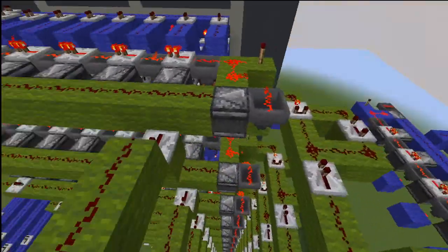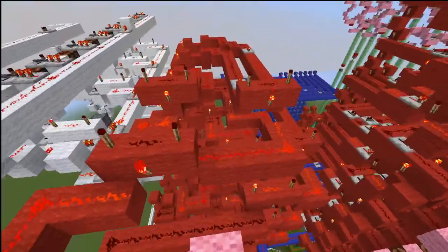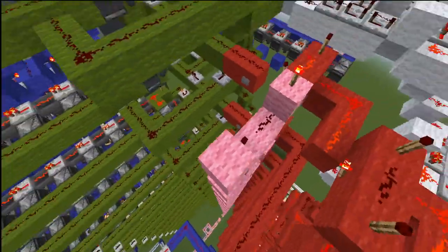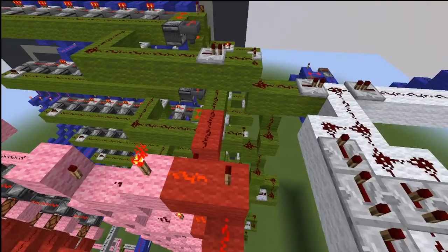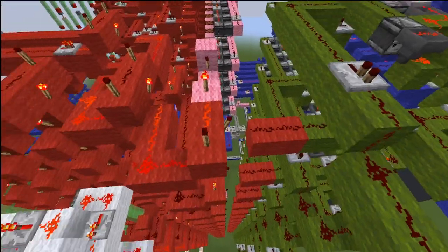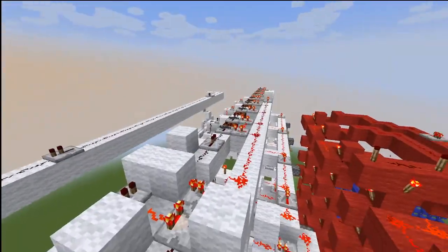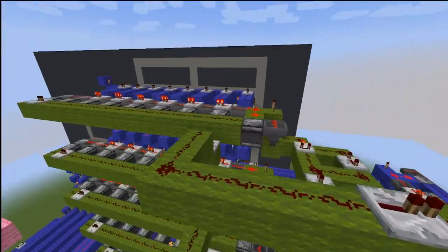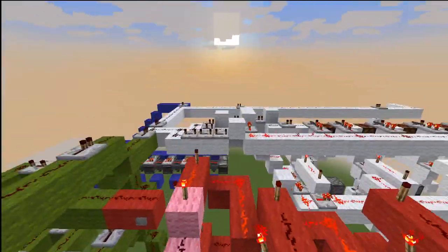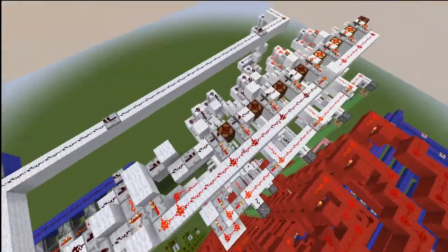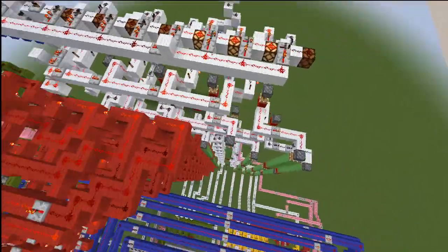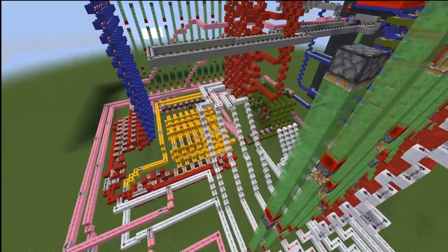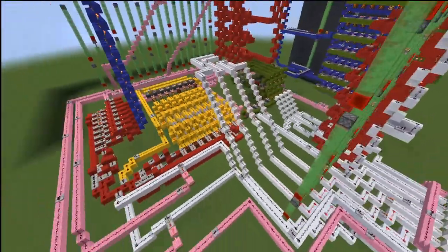And then you have right here, this red part here is the memory address register, and this works in conjunction with the control unit. So when it gets a signal, the memory address register will select the location that it needs from the data it receives from the serial and data bus, which will select a line from PROM here and send it to the address and data bus in serial, which is here. And then this data is shifted downwards and then split from serial to parallel and then taken from parallel buses to other components of the computer where it may be used.